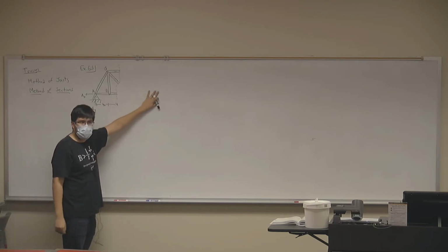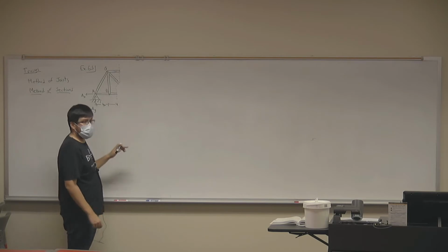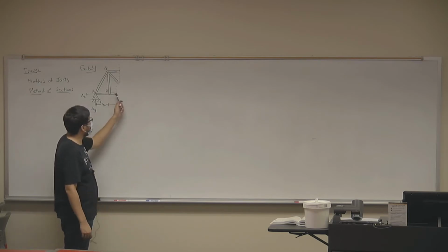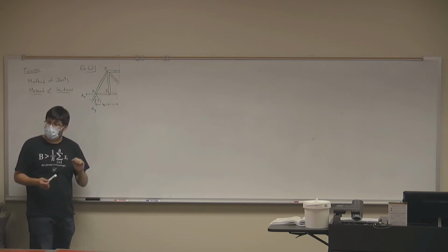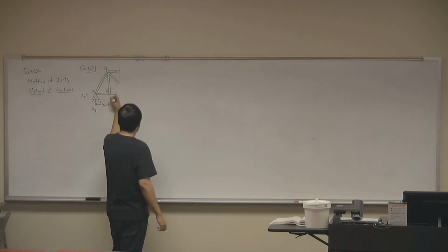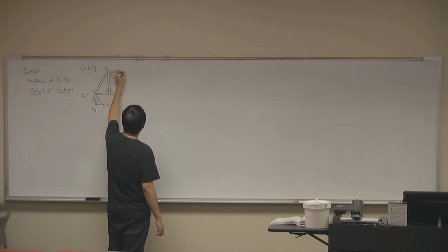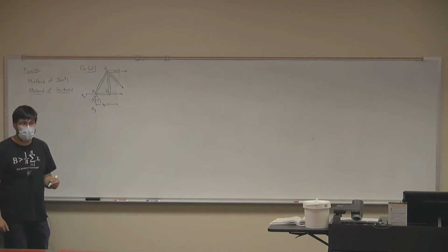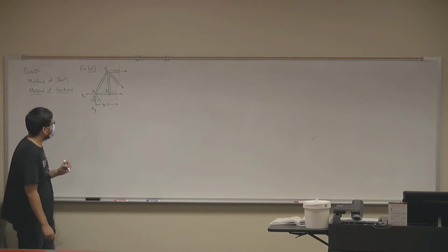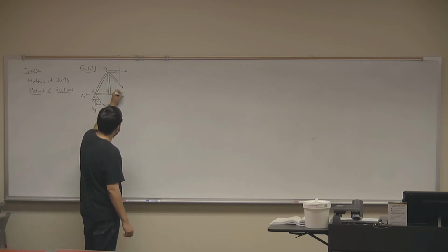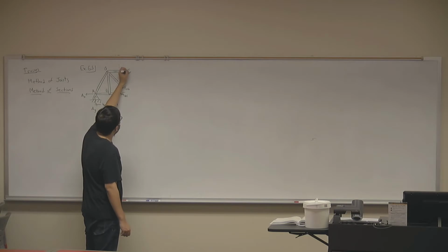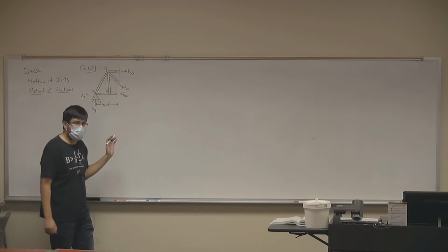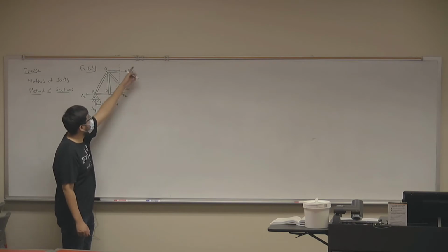A lot of these forces disappeared, right? So how do we make up for those forces? We're going to make up for those forces by considering tensions and/or compressions in these trusses. In other words, once you make your cut through your trusses, you need to consider that each truss will have a tension or compression associated with it. Okay? So what this gives me is a force from B to C, a force from G to C or C to G, and a force from E to G.